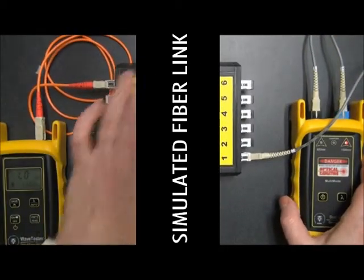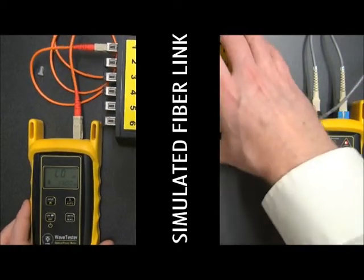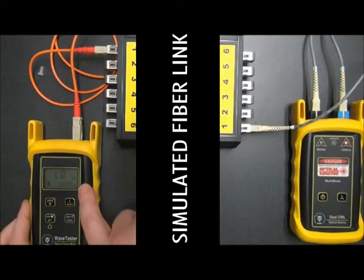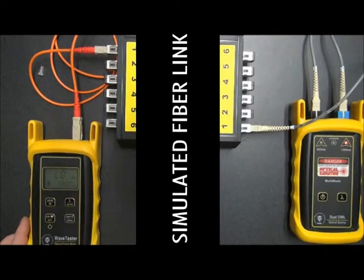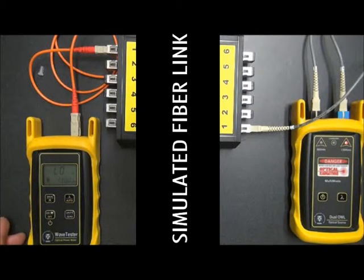Okay, now you can see that the power meter says low here. Remember, low means that there's no measurable amount of light coming into the detector. It's because we're not on the right wavelength. So let's switch the wavelength to 850 nanometers on both units. All right, and now you see we have a reading.